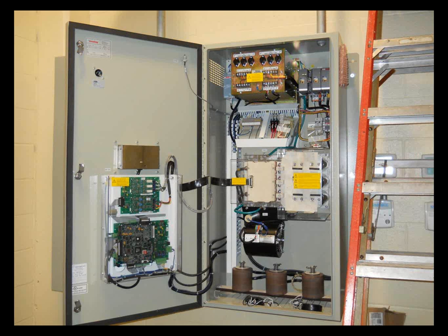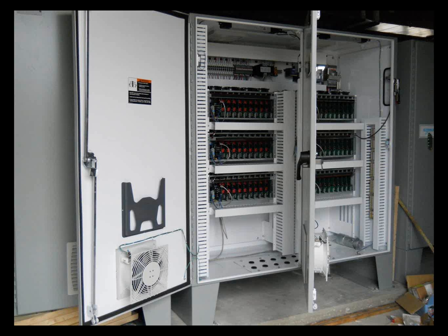This is one of the two filters we have in here. These filters actually clean the power. One of the things you've got to consider is your line power coming in and your generator. How much variance in current is there? If you're like us, even though our power company swears their power is constant, it's not. And so you want to make sure you have a good, clean source of power so that you don't burn ballasts and bulbs up prematurely.